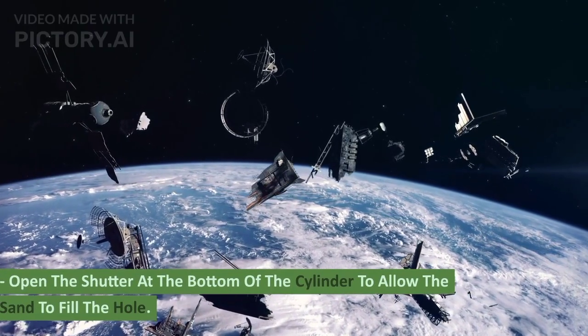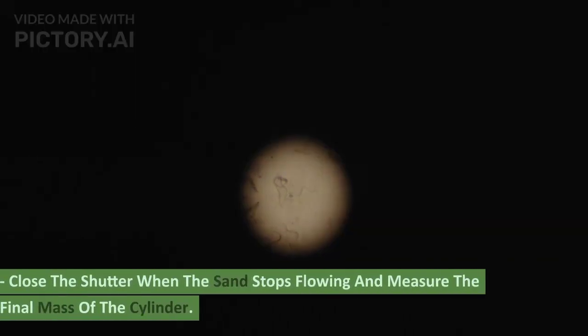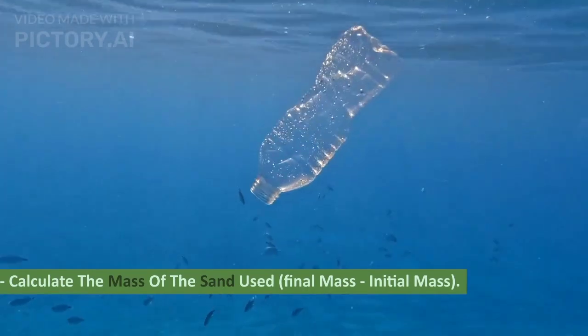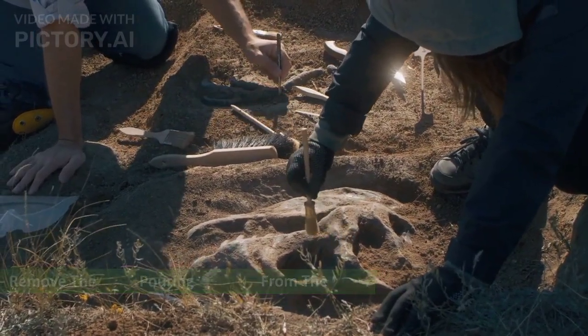Open the shutter at the bottom of the cylinder to allow the sand to fill the hole. Close the shutter when the sand stops flowing and measure the final mass of the cylinder. Calculate the mass of the sand used: final mass minus initial mass. Remove the sand pouring cylinder from the hole.